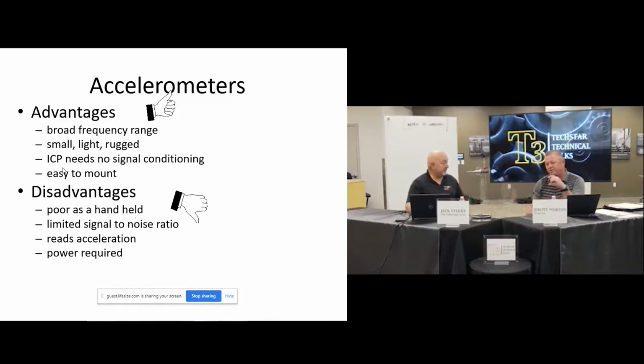So when we talk about a velometer or accelerometer, they're very similar in how they're built and designed, with basically the main difference being the accelerometer has an integrator circuit that's built onto it. That's what it is. Pay attention when you pull one out of the drawer, because you don't know if you've got a velometer or an accelerometer. Most of them look identical when you hold them.